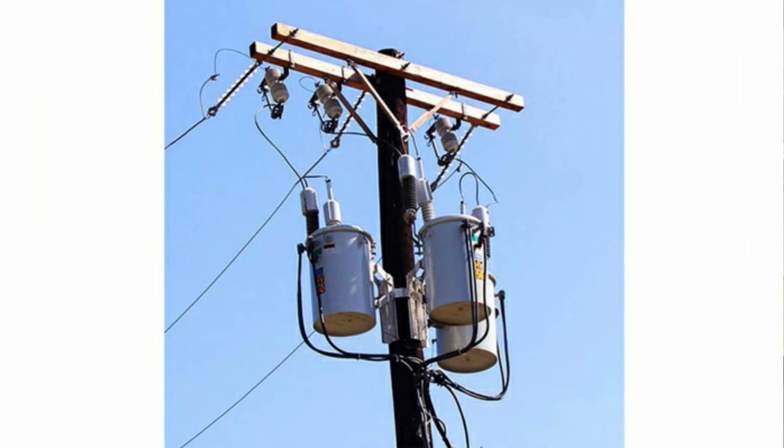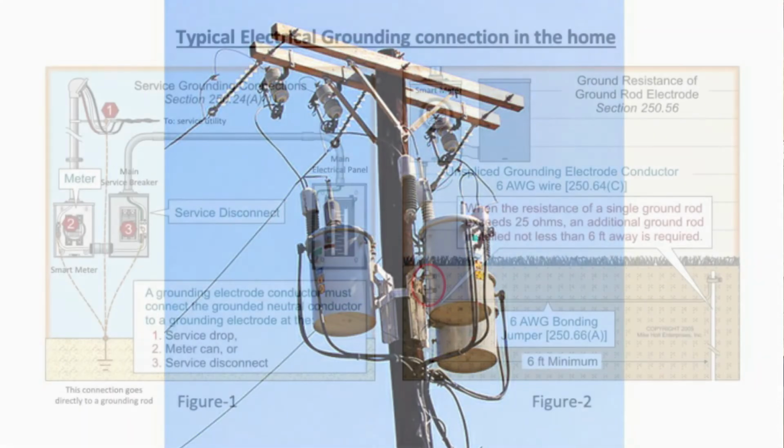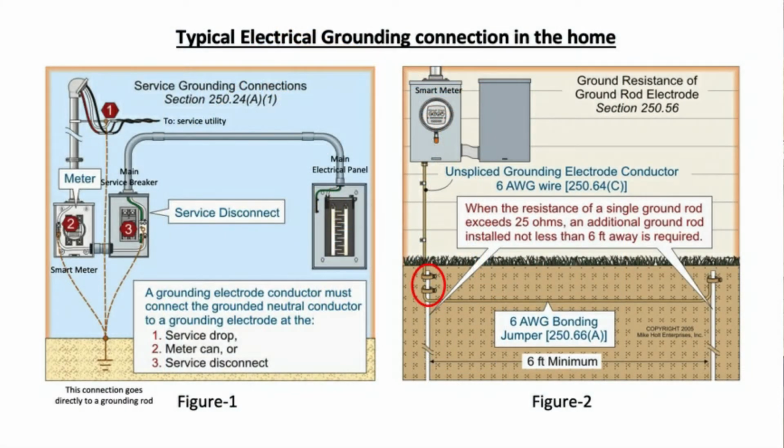That's the transformer stepping down the really high voltage that's transmitted and distributed throughout the city to a safe level, where we've got those 3 wires that I talked about earlier that come into your home. And they give us our 208 volts and our 120 volts here. It gives us all the power that we need.